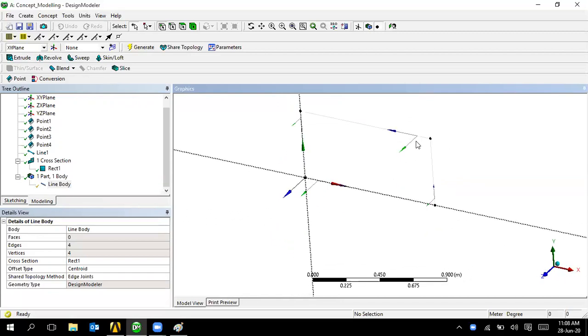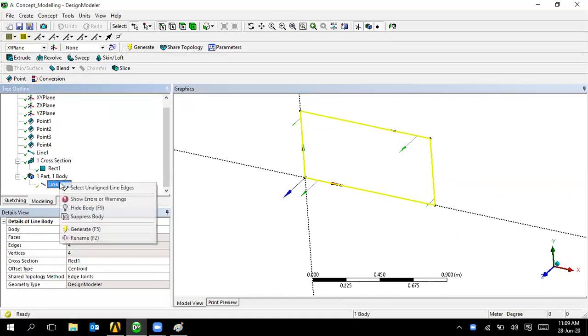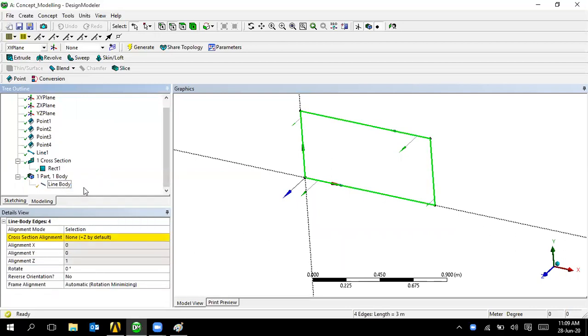If the y-axis falls on this side, then it will become proper. So now it is not proper, so you need to flexibly change these things. Look at here: right click, align. Look at this positive y direction. Set this thing to positive y direction.